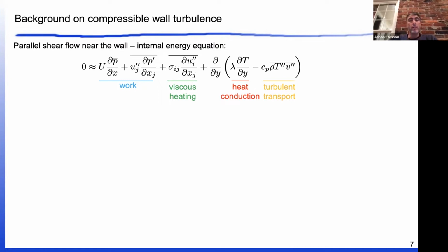So you have this flow of energy where kinetic energy in the mean field, through production, turns into turbulence kinetic energy. When the turbulence is dissipated, it's dissipated into heat. That becomes a source in the internal energy equation. The remaining terms are pressure gradients multiplying velocities. The pressure gradient is a force per unit volume, so these are work terms, but they tend to be smaller. By and large, if we combine all of these, we basically have a source of heat that is approximately equal to the viscous dissipation rate.